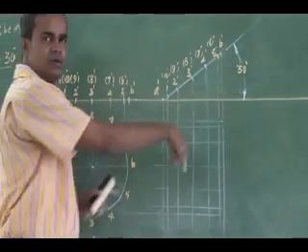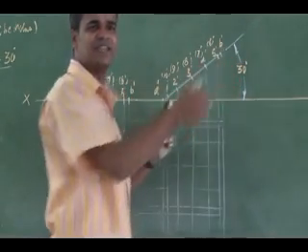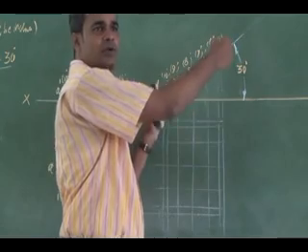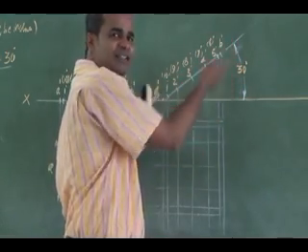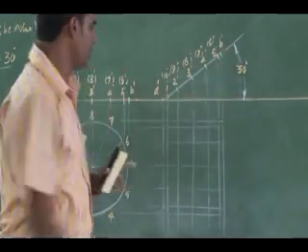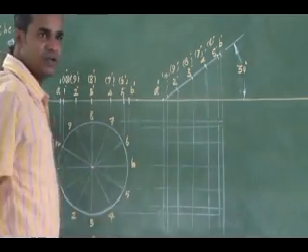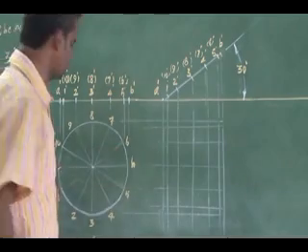See here, I have redrawn the front view to 30 degree inclination. That is this surface inclination. Okay, the line is seen in the view, then the surface is inclined 30 degree. That line is tilted to 30 degree. Now I can get the previous second step top view. Okay, the final top view, the appearance how it will be. This is going to be the top view.